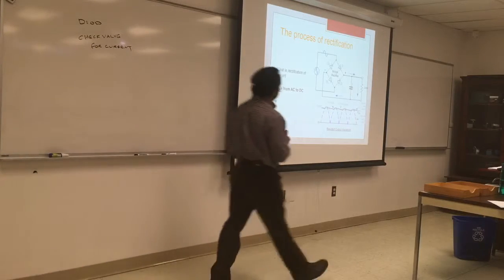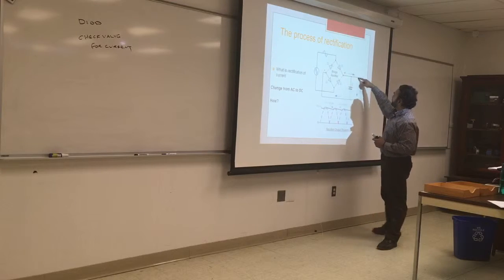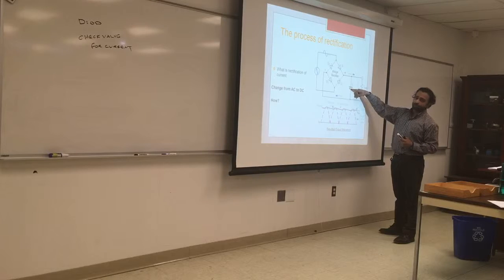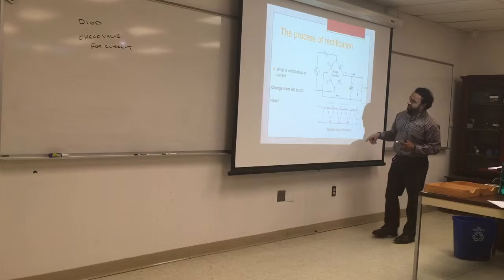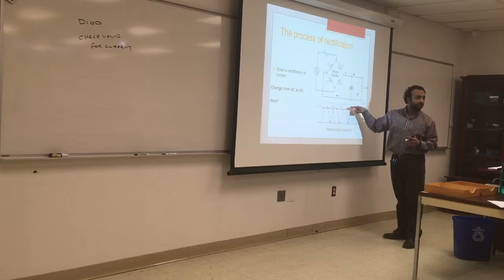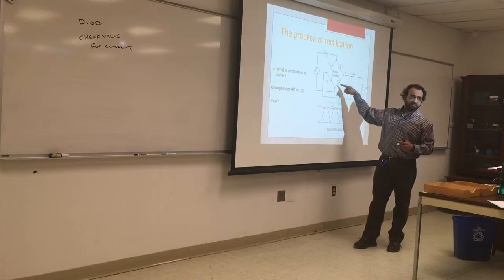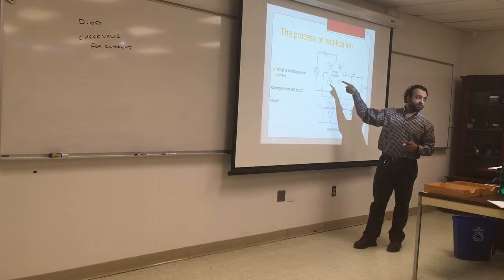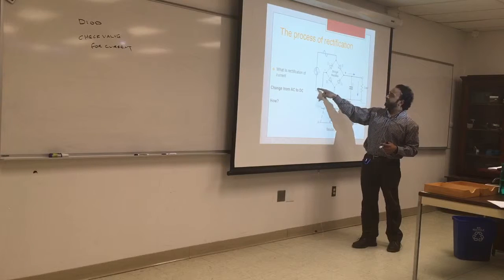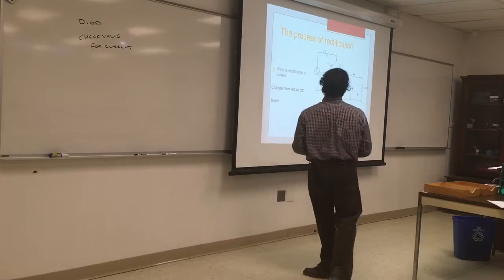So these are diodes. This is my AC going in. It goes to the rectification system here. We have a capacitor that will hold a charge. What happens here is, as you see the sine wave going up and down, we're shaving only the top, which is the peak voltage. Through this rectification, we'll have it running in one direction, and eventually you'll get DC coming back into the flow.